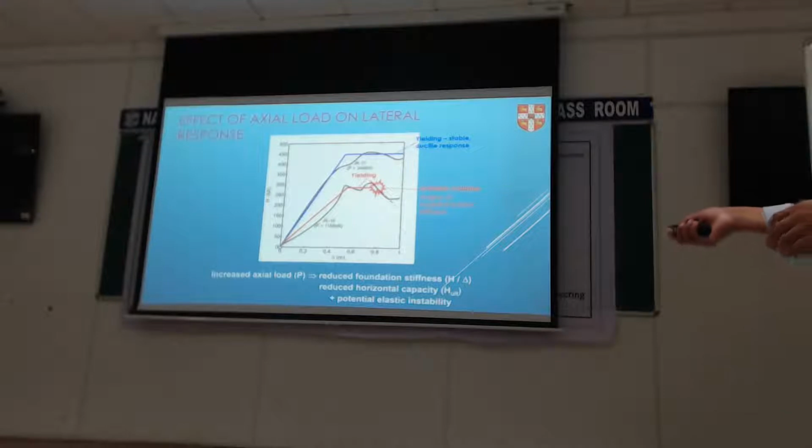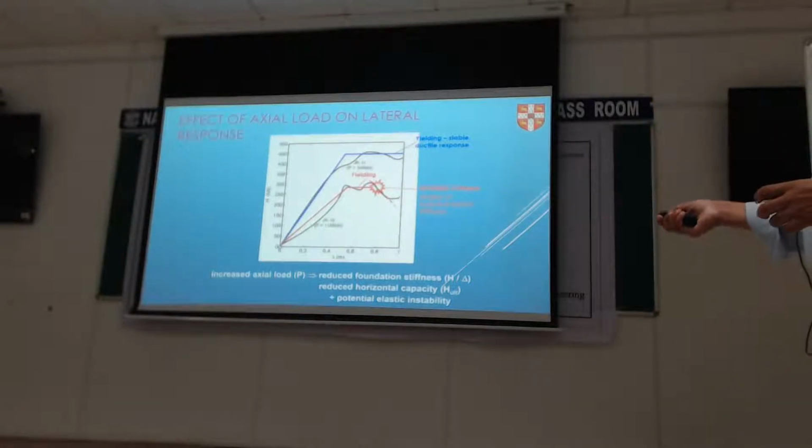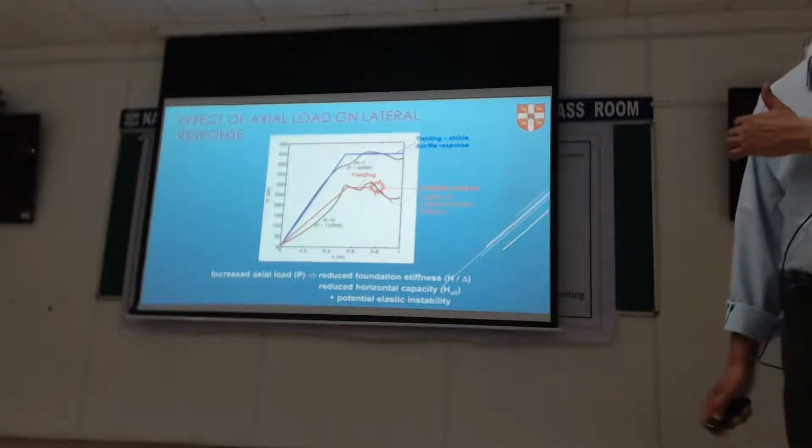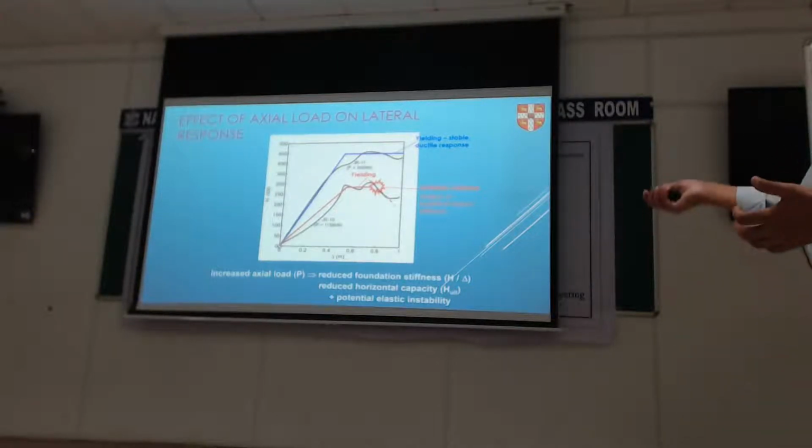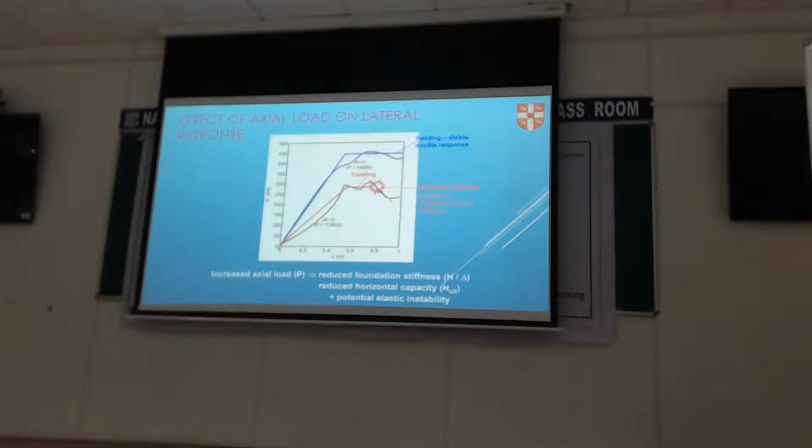So you go up linearly, elastically up to yield, and you deform in a ductile fashion after that, which is considered to be stable from a structural design point of view. In fact, you can work out your ductility factor depending on how big it is. The black line, which is coming from the experiment, seems to more or less do that with some minor kicks up and down.